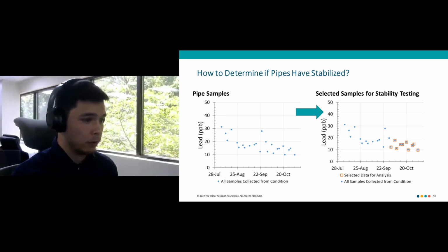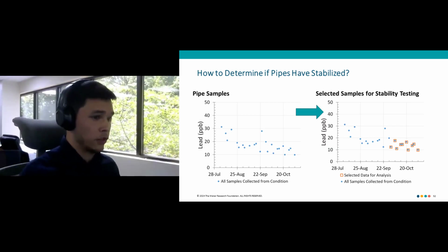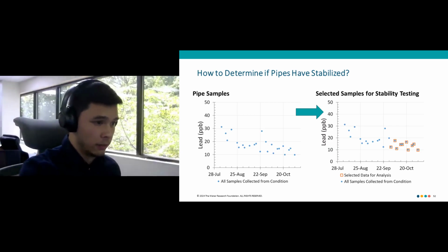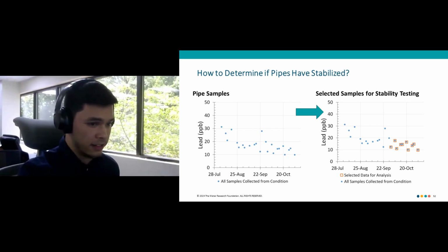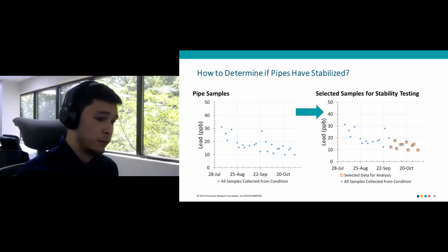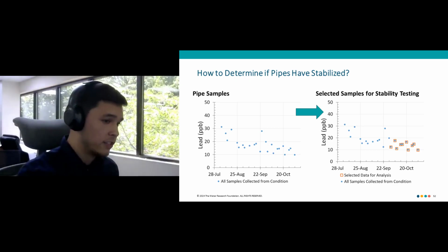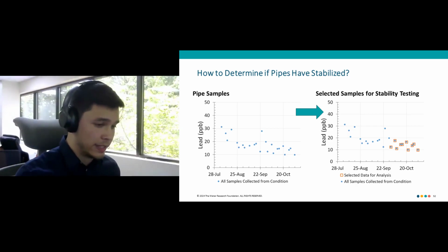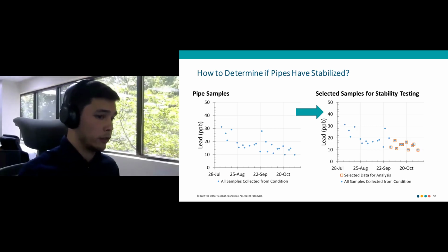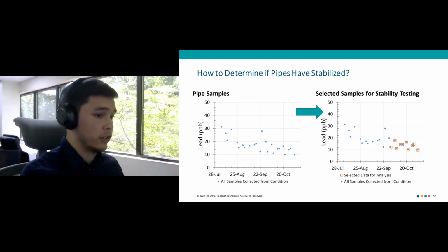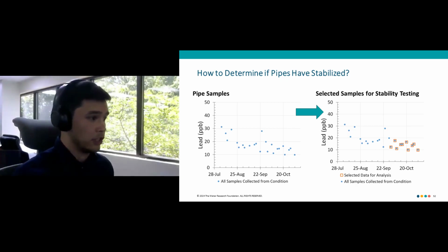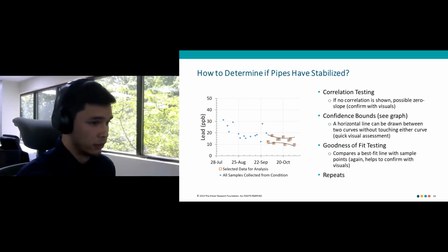stabilization process of grabbing points very quick, because when I started out doing all these tests, showing you this example, I had to grab these 10 samples from a visual inspection. And of course, if these 10 sample points failed at statistical inspection, you'd have to either wait for additional data points to be taken, or go and grab a new or additional set of points to see if stability has been achieved. So this can be a very tedious process, but it is very helpful using both the visuals and the statistical methods.